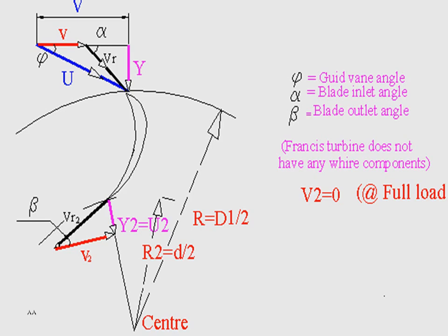If the runner rotates in clockwise direction, we have the tangential velocity small v in the red color equal pi D N over 60, and we have here Vr, the relative velocity of water as it goes at the inlet of the turbine runner. The total absolute velocity will be capital U, which from the equation equals v plus Vr vectorially.